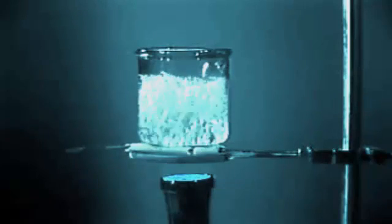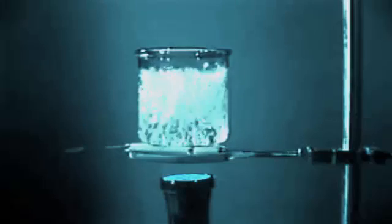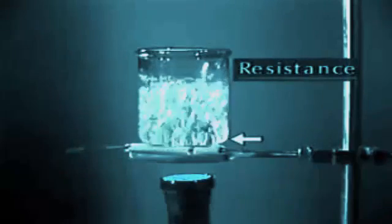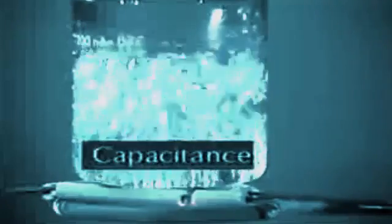Now, in a thermal process, that is, one involving heat, resistance and capacitance may be somewhat different. Here, a flame is used to heat a beaker of liquid. In this arrangement, the wall of the beaker represents the resistance, since it resists the transfer of heat from the flame to the liquid. The amount of heat or thermal energy that the liquid is able to store represents the capacitance of the system. Process characteristics such as resistance and capacitance can affect how a control system responds to process